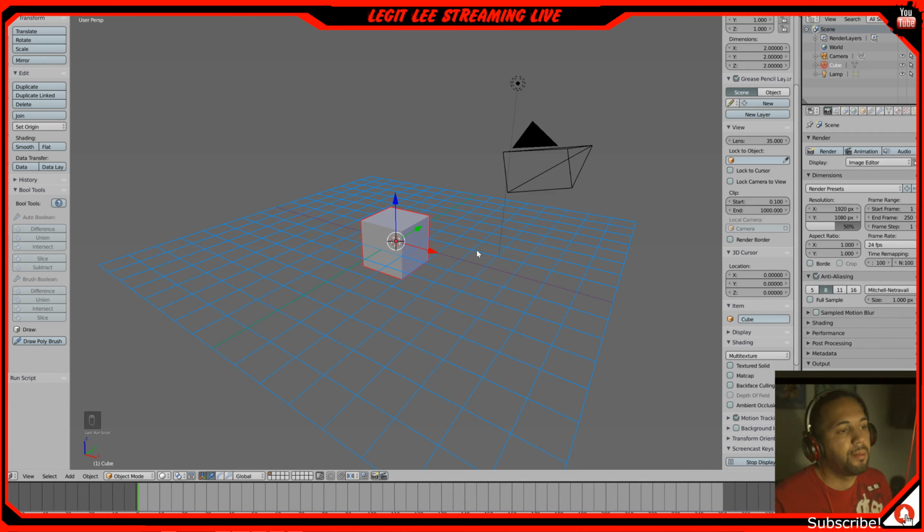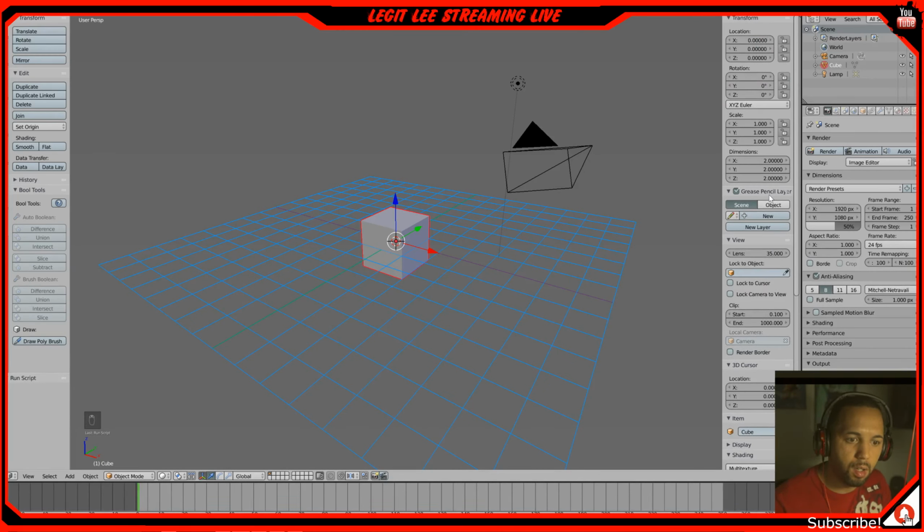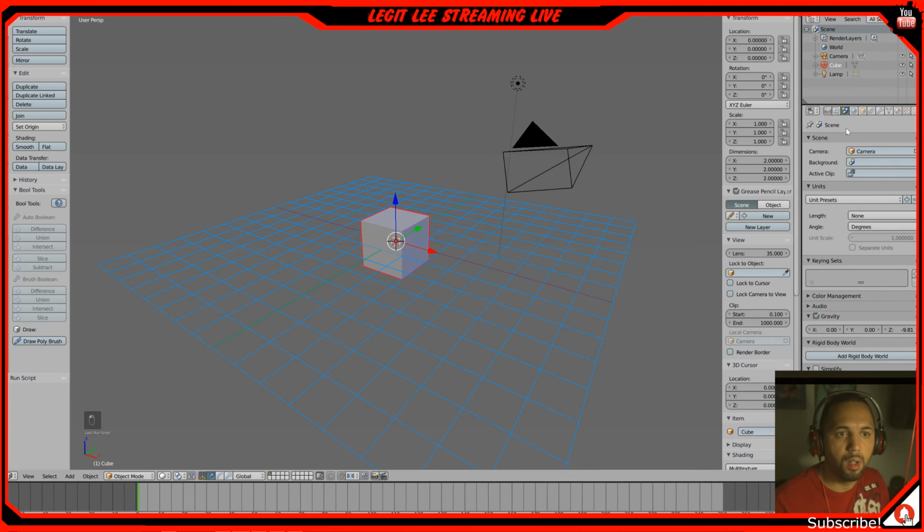Anyway, so now that we're in Blender, we got our panel up. Let's go ahead and start getting everything set up properly. So we're gonna do millimeters, because like I mentioned before, 3D printers use millimeters for the measurements. So we're gonna go into this display data, basically active data to display. We're gonna go down here, do millimeters again like I normally do. Now we're in millimeters in our units. That's what Blender is currently viewing.